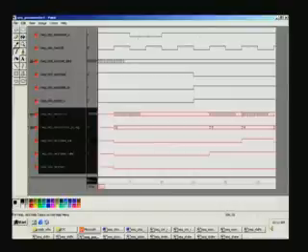So here, as usual, a reset is applied, and this is set data. Here also we are setting the same 1010 pattern, and a shift register, what happens internally, there is a 16-bit shift register, and that is preset to the same 1010 because that is what we want, and at the positive edge of the clock because code has been written like that, and this is the counter to keep track of the number of bits.